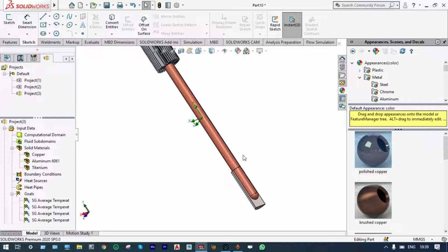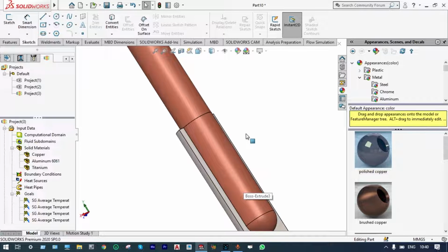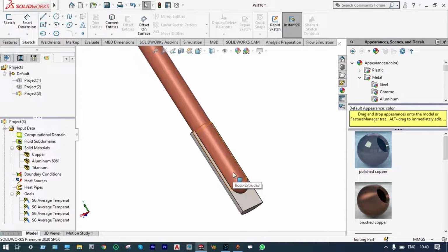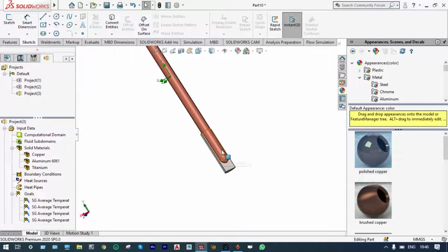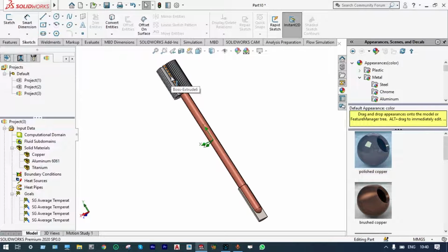Now, heat pipes may be of different types. What is there inside these heat pipes? Actually, some kind of wicks are provided, and if we provide heat from the bottom source, the liquid will be evaporated and will flow from down to top, and again it will come back from top to down because of capillary action. For better understanding, let us cut the heat pipe from the middle section and show how it works.